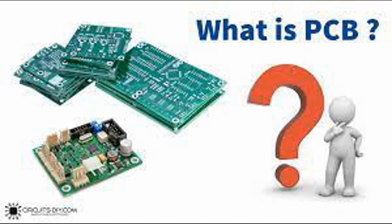Reference designators. Each component on the PCB is assigned a reference designator, such as R1 for a resistor or U1 for an integrated circuit. The silkscreen layer often includes these reference designators alongside the corresponding component locations to assist in component placement and circuit debugging.